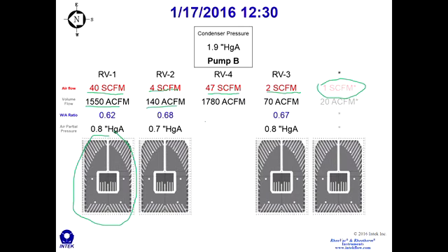We have a 1/10 of the capacity here, and a 20th of the capacity over here. And so this bundle is dominating most of the pump capacity. And so, since the air and leakage is here, the pump capacity is here, we know that this is causing an issue, an imbalance in the flows leaving the condenser.